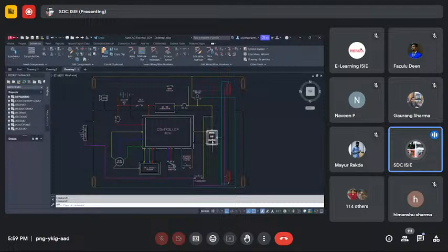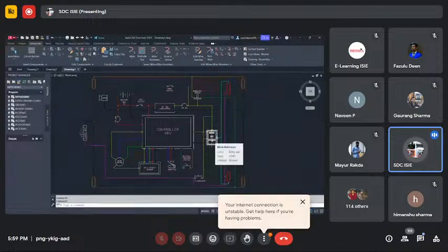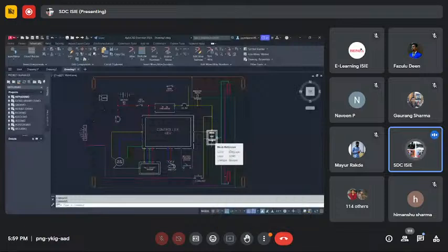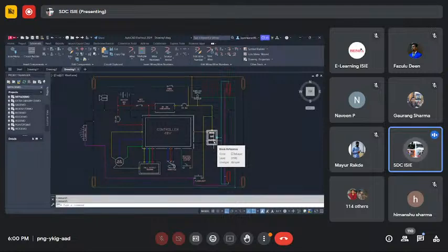The brake cut switch is connected to the mechanical part to disconnect the power from the controller to the motor. And we have a push-pull connection switch on the yellow color wire also, to indicate that when we apply a brake, you can see the brightness increase in the back light. Due to the brake cut switch only, we have one push-pull button also in the brake cut switch.